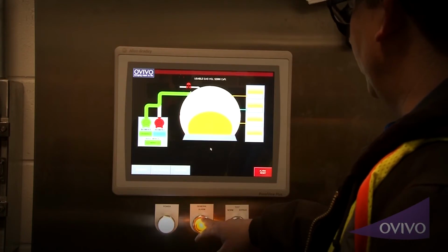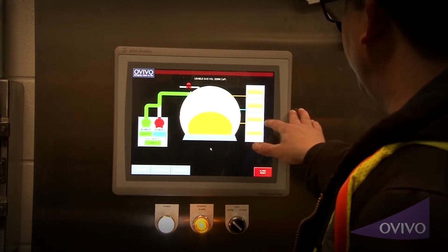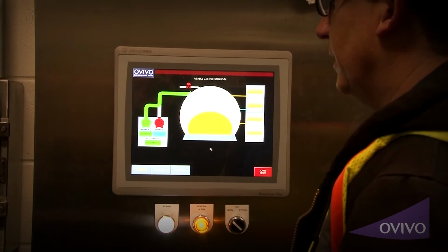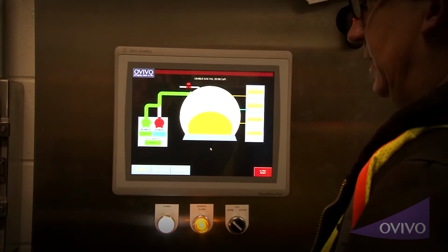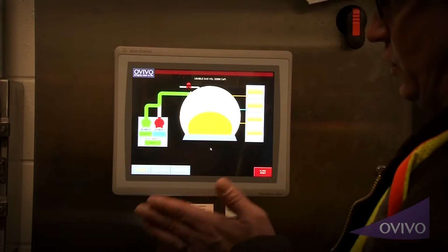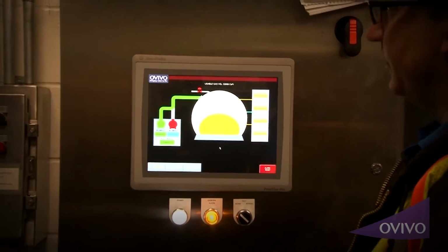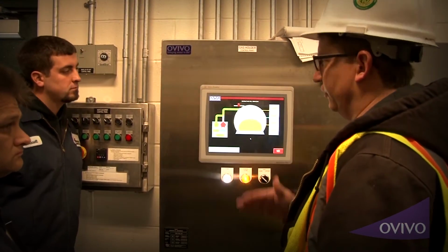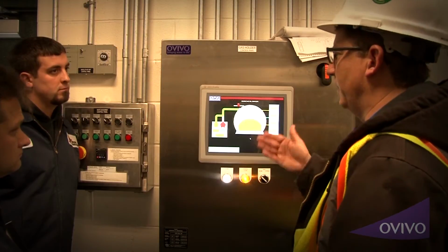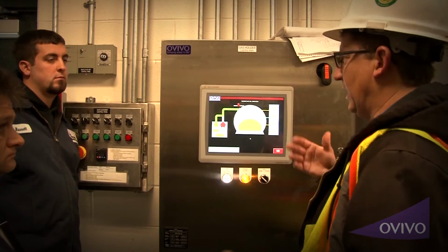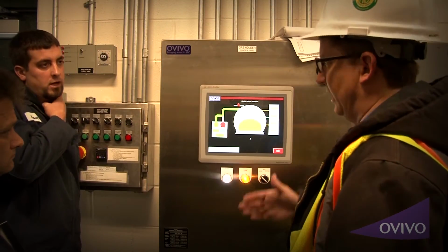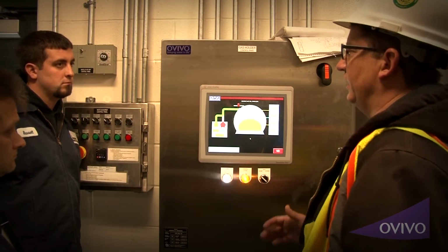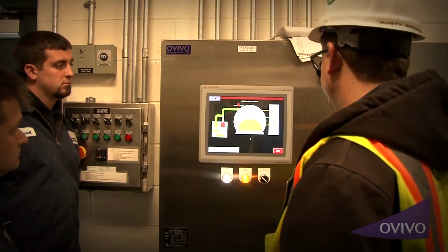Other than that, the general alarm will go off when everything gets set up with the gas pressure sensor. 25% is here, when it gets past the alarm point, does it go in and out, in and out? Yeah, it's not going to go from 20 to 21 to 20. No. It's got to go up to 25 now. And hopefully you have some volume. So you're not actually just triggering purge mode on and off. It's actually going to go up to 25, shut off. And then if it's using air or gas or something like that, then hopefully you've set the alarms. You've actually addressed the situation and are trying to get more gas into it.